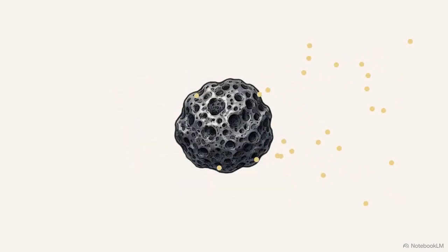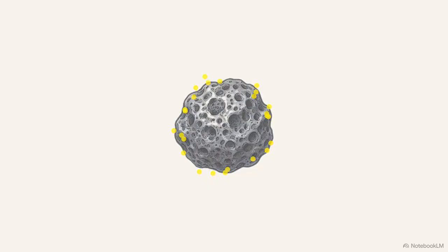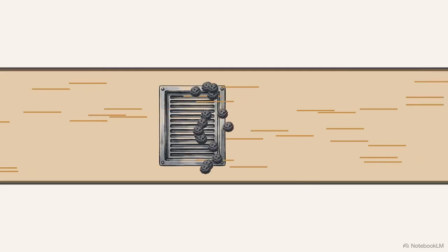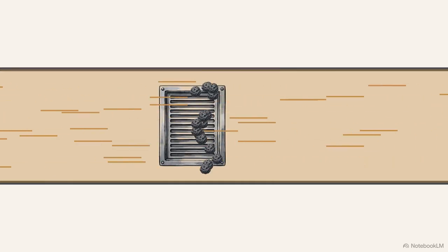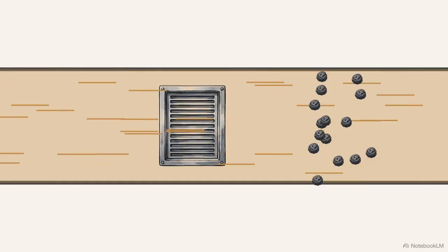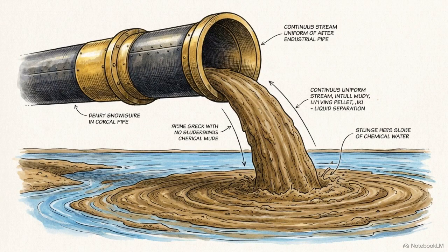A mechanical risk is gold-loaded carbon washing out with the mud. To solve this, bridge screens at tank exits trap the carbon pellets. Bursts of compressed air blast across the screens, preventing clogs and allowing only barren mud through. Through this precise mechanical choreography, the gold is separated from the sludge, without a single drop of liquid ever passing through a traditional filter. The gold is out of the mud, but it is now chemically trapped inside solid chunks